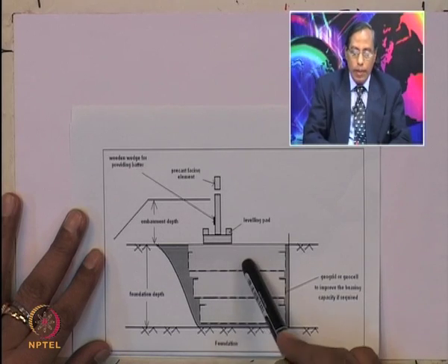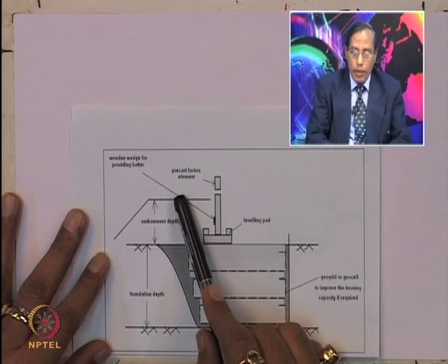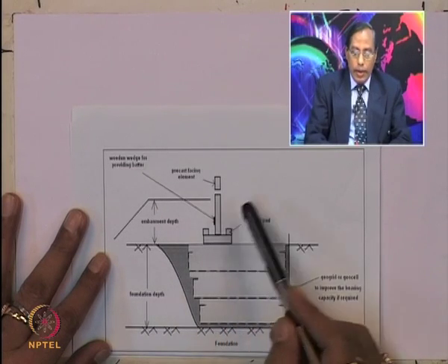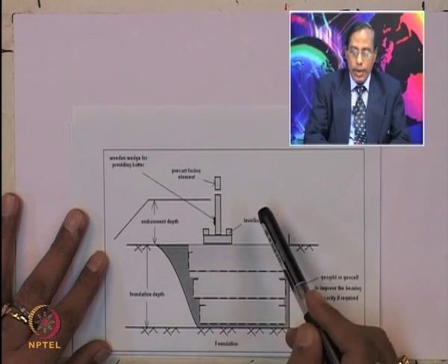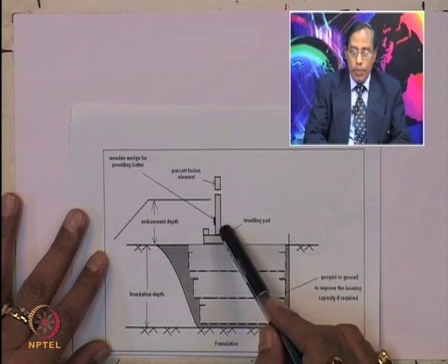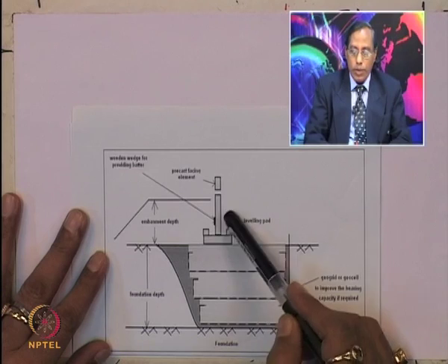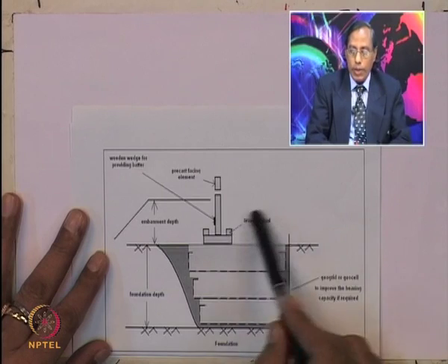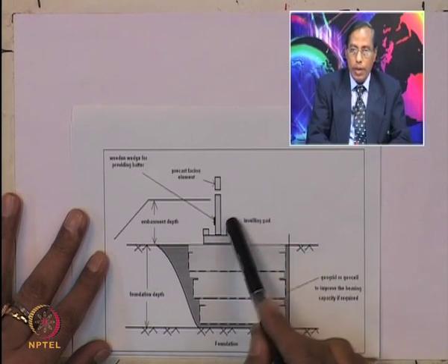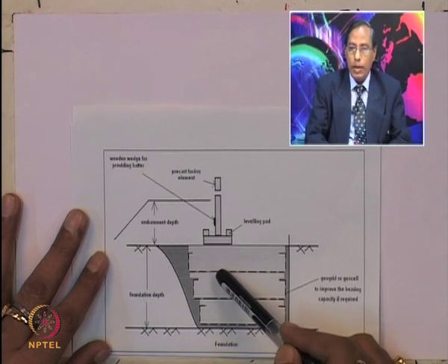the bearing capacity if required, and you have to provide certain embedment depth here, and this panel or the block, which could be the wooden wedge for providing the batter, and this is the leveling part in which that precast concrete facing element will rest. This is flexible like a hinge, and then reinforcement will be on the other side. It can be resisted by the reinforcement. So, this is the geogrid layer at the foundation, how the foundation subgrade can be improved.